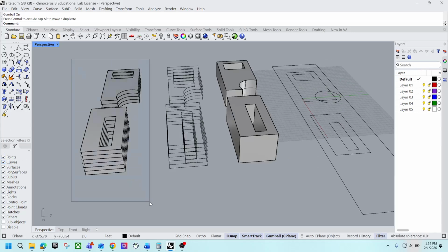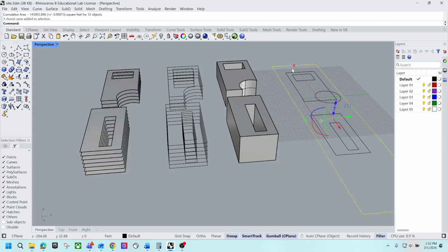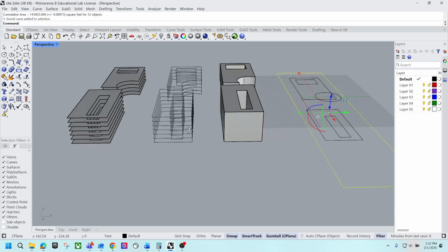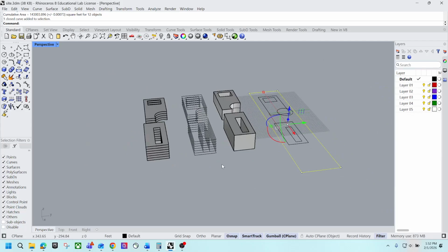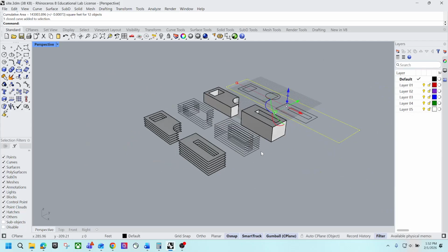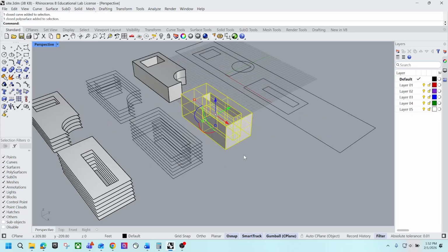So now I have these floor plans, right? At this point, if you type area, what you get is the total construction of the building, right? And then if you divide this value by the site, you have the FAR. Make sense? Yeah, so this is the whole process of how you can generate these two values, BCR and FAR, just by siting the massing model. I do want to say this could also be super useful.